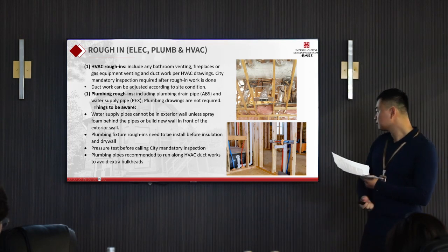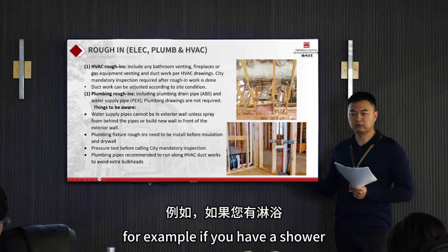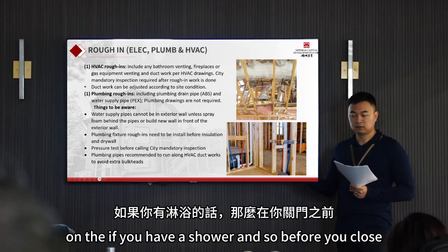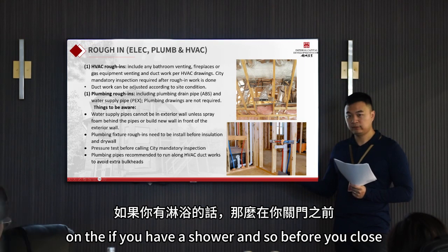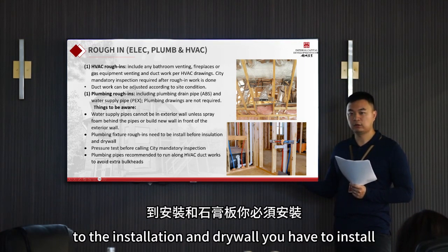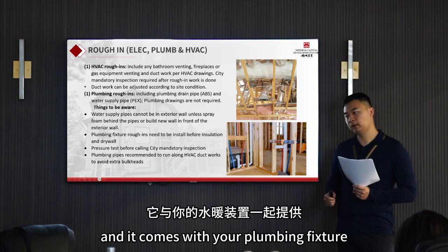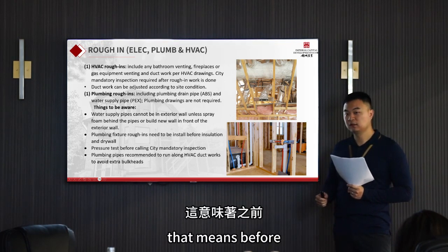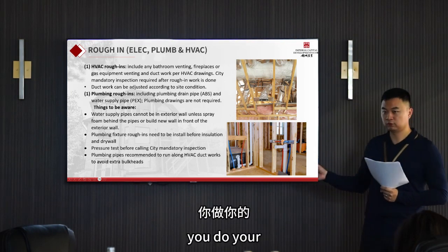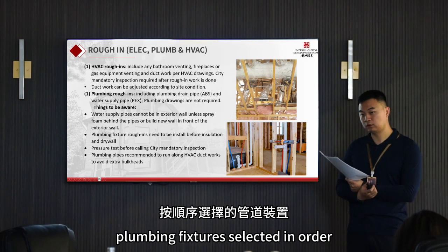This photo doesn't show it well, but for example, if you have a shower, before you close in with insulation and drywall, you have to install the plumbing fixture roughings, and it comes with your plumbing fixture. That means before you do your plumbing roughing, you have to have your plumbing fixtures selected and ordered.